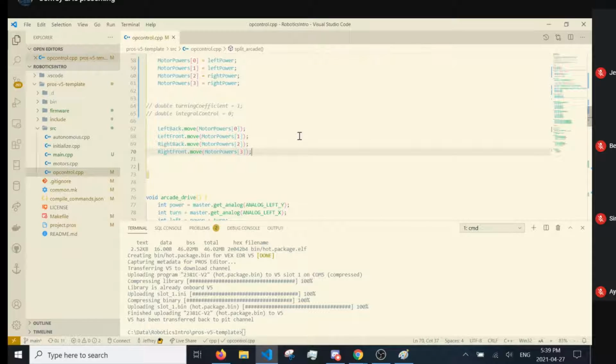With only feedforward control, the only things we're allowed to control are the voltages. With feedback control, we can control any variable that we can A, measure, and B, model. And this demonstration shows that we are in fact setting the speed of the motors now instead of just setting the voltages.